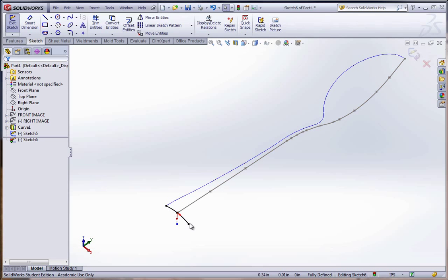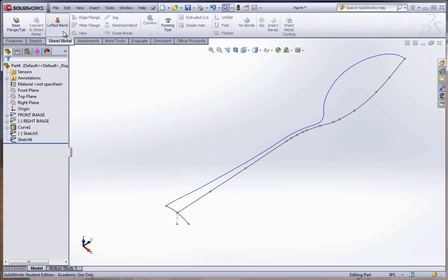Because we pierced that curve, this spline will follow through on this end, basically matching what it sees on the left side. Sometimes I've seen where it kind of veers off a little bit. In this case, it's going to be okay, but if that's an issue, then you might want to make another guide curve for the opposite side or do some mirroring. Okay, now we could hit rebuild, and we're ready to test this.